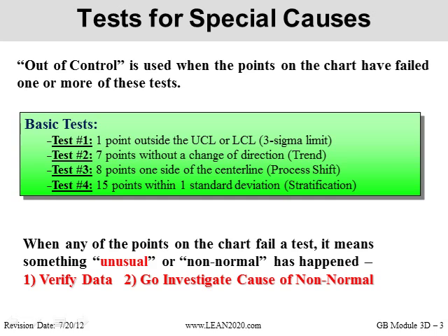This is how to interpret a control chart. The nice thing about this is once you are able to interpret a control chart, you can look at data from any process representing any particular environment and be able to discuss normality. Is the data usual, normal or not normal? So when we see a point that fails a test for a special cause, we're going to consider that data not normal, and again, that condition would be out of control.